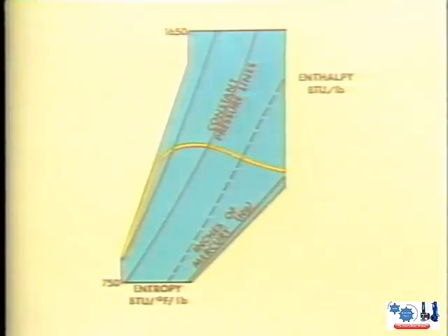For most purposes, the approximate value from the Mollier diagram will be close enough. Another thing that you should know about the constant pressure lines is that at pressures lower than atmospheric, pressure is indicated in both psia and inches of mercury. This is simply a convenience for the operator, since pressure lower than atmospheric is often indicated in inches of mercury. Showing both scales on the Mollier diagram keeps you from having to convert between the two units. These values are often here on the diagram.